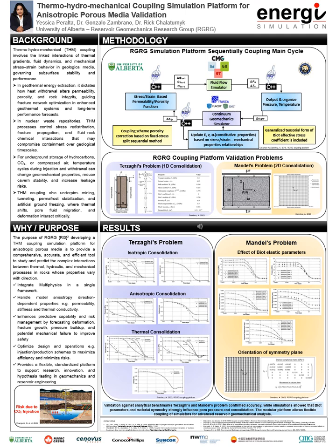After reaching the equilibrium, the updated stress and strain tensors are used to calculate the new porosity, pore compressibility, and thermal expansion coefficients. These corrected values are sent back to CMG, ensuring that the next flow steps account for geomechanical effects.